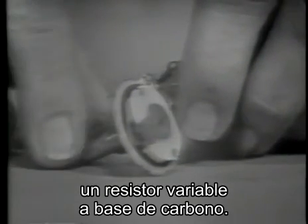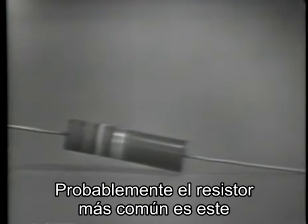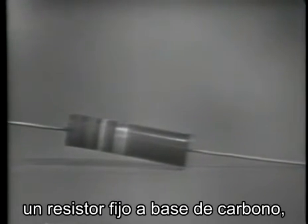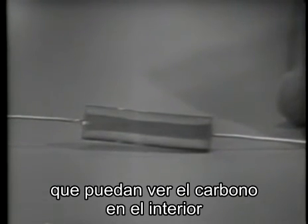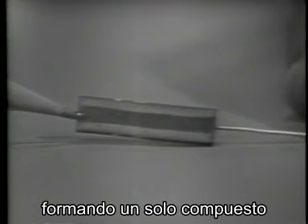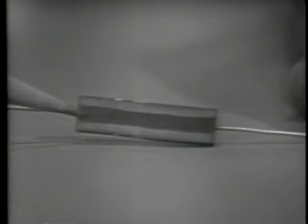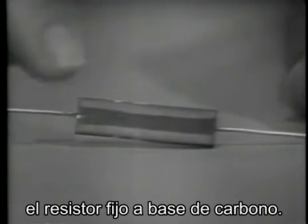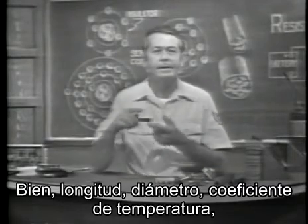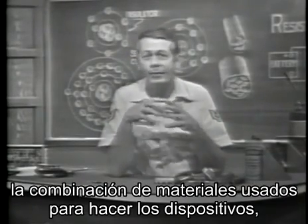A variable carbon resistor. Probably the most common resistor is this one, a fixed carbon resistor. I've cut it in half so that you can see the carbon compound inside. This carbon rod has a fixed resistance. It's made of carbon, materials such as rubber, talc, things like that. Probably the most common type of resistor used. The carbon fixed resistor. Okay, length, diameter, temperature coefficient, the combination of the materials used to make up these devices all determine resistance.